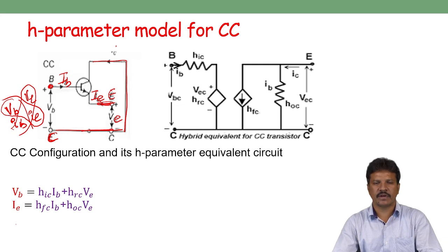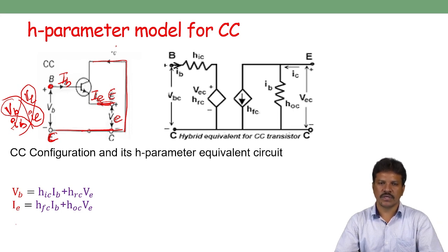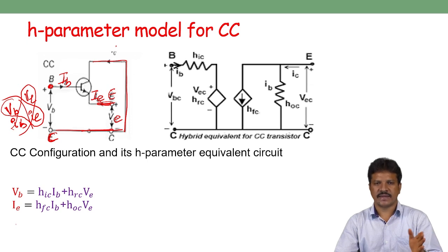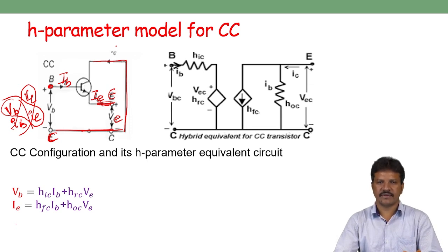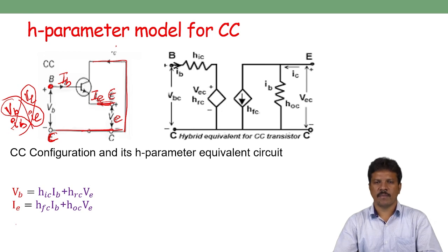The main advantage of this model is that we can analyze accurate values of the transistor amplifier parameters, like input impedance, output impedance, voltage gain, and current gain. So in order to get accurate amplifier parameter values, we must replace the three-terminal transistor with the H parameter model. It is very easy and accurate. So these are the equivalent circuit diagrams for the common emitter, common base, and common collector models in two-port network analysis.